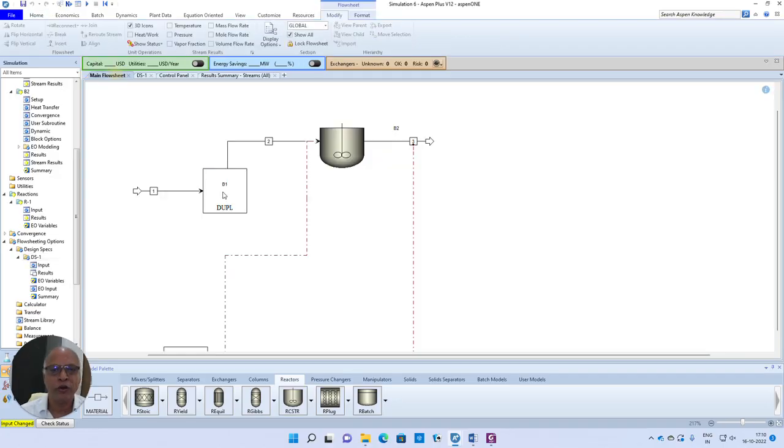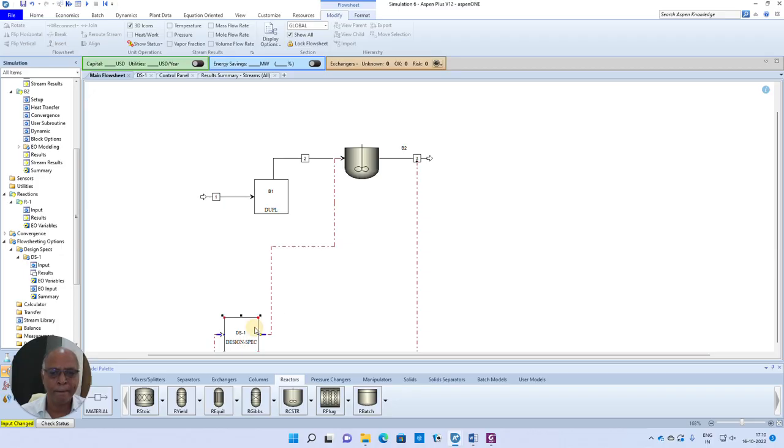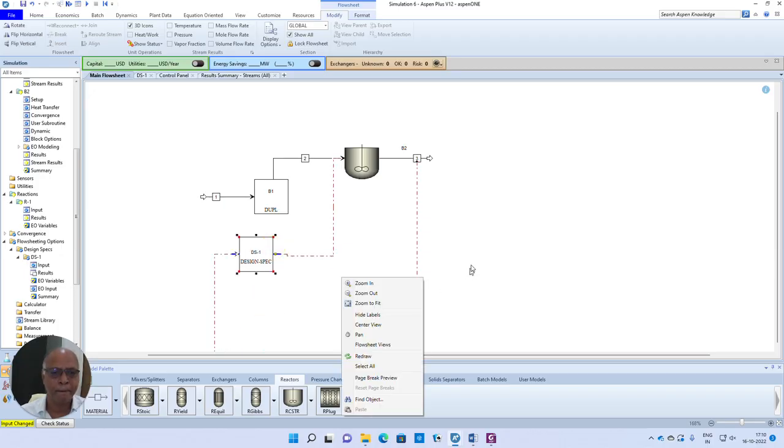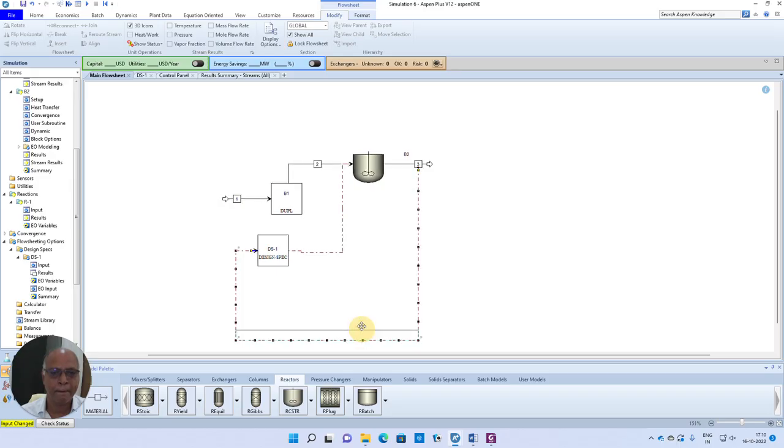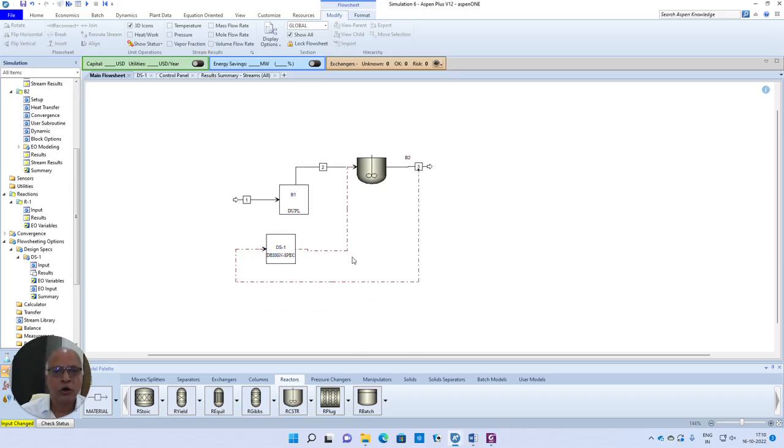Now once again, you can see this is what is going to happen. We started with some volume, which is 1 cubic meter. Calculate the exit flow rate. So 1 minus FA should be equal to 0.6. Compare whether you got that result or not within the tolerable limit. Then if it is not reaching a convergent solution, you go back and readjust the volume. So this is how the design spec is going to operate. Let us run this problem.